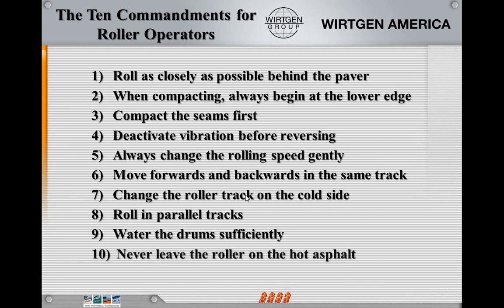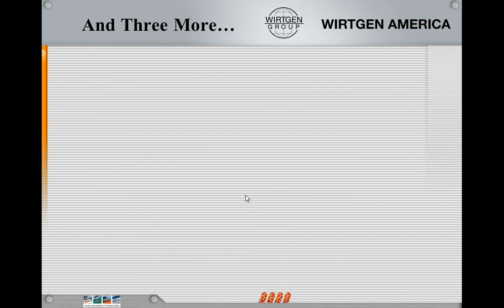Never leave a roller on the hot asphalt. If by any chance you're going to stop, if you can pull it off the hot spot or hot mat, put it on a cold mat, that'd be great. Don't stop behind the paver and sit there and chat with the guys behind the paver.